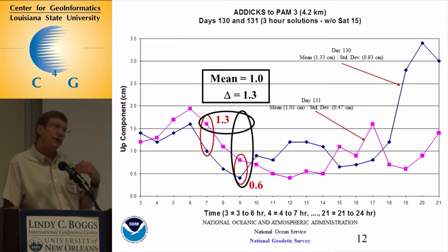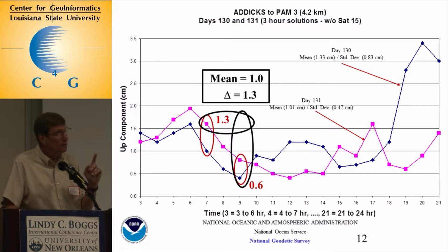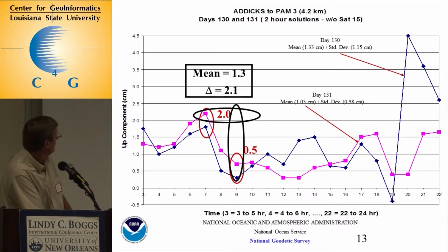Remember, you're trying to detect, reduce, or eliminate error sources. And that's why you got to do observations and repeat them at different times and so forth. New technology, new procedures, using networks, this is what you got to ask yourself when you talk about real-time networks and how you're doing it. Are they detecting, reducing, and eliminating these error sources that you're doing in a static survey? Are they handling the atmospheric effects? Are they handling the geometry differences? Those are the kind of things that real-time networks should be doing and are doing, and will vary based on that.